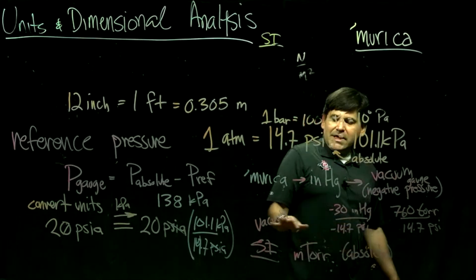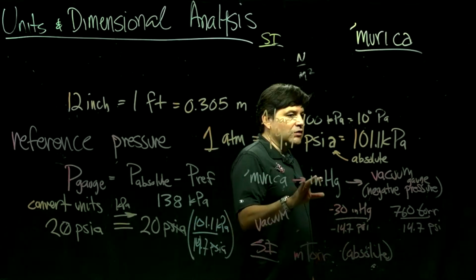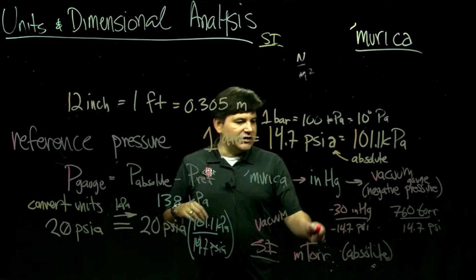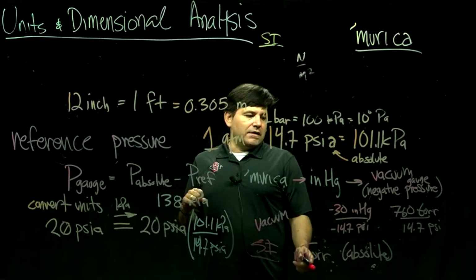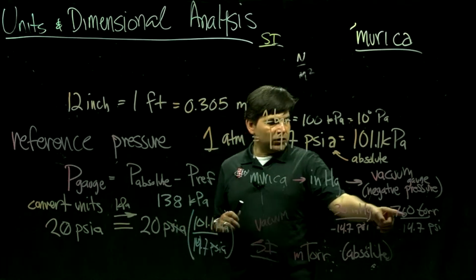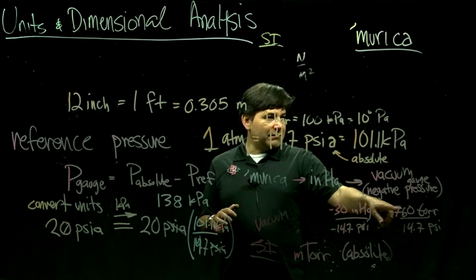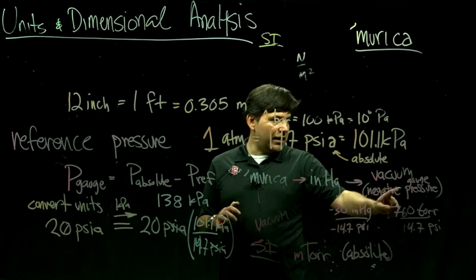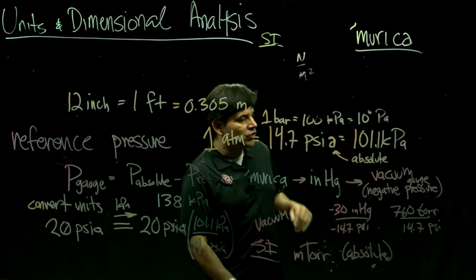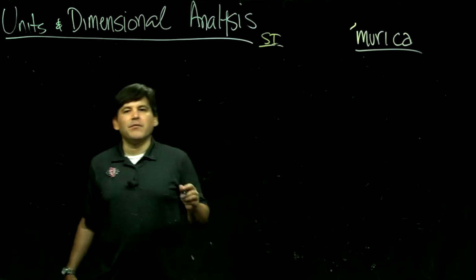And in SI units, when you're talking about vacuum systems, we often use millitorr absolute, so it's trying to stay like millimeters of mercury rather than inches of mercury. And they're trying to be even smaller than 1 torr. So 760 torr gets you from 0 to 1 atmosphere. And then vacuum systems operate on the millitorr scale, which is trying to get to like a 1,000th of 1 torr level of pressure. Okay, pressure is part of the ideal gas law.